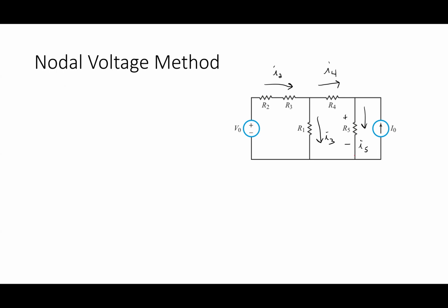All right, so when I look at this guy right here, the way I think about the node voltage method, we set one of our nodes to be ground. So in this case, how many nodes does this circuit have? Technically it has 4. Yeah. All right, so I got one here. I got one here. I got one here. I got one here. All right, now how many unknown nodes do I have? 2. All right, so you always set one to be 0.